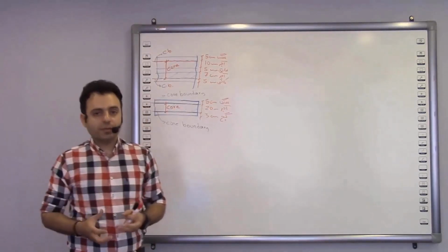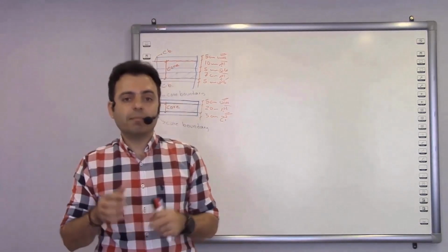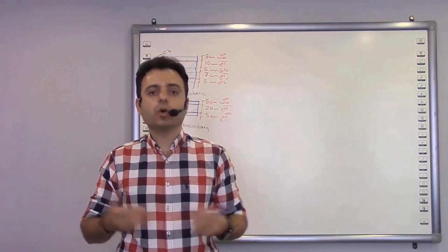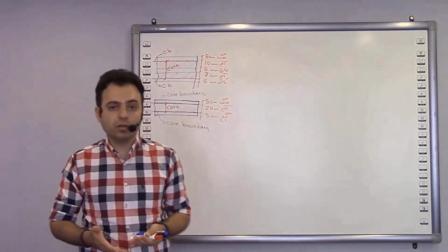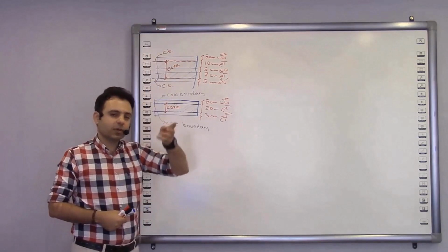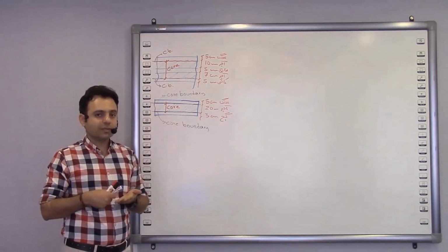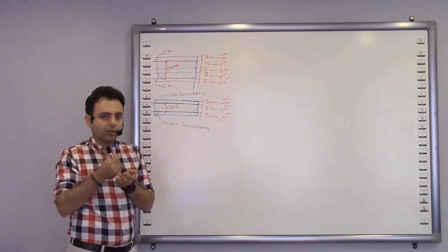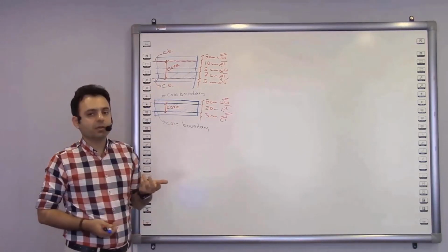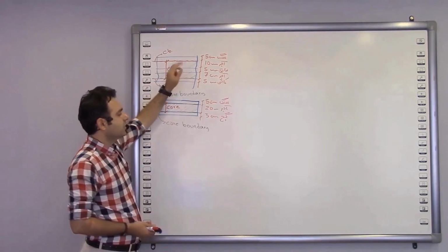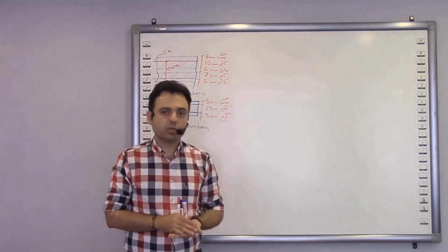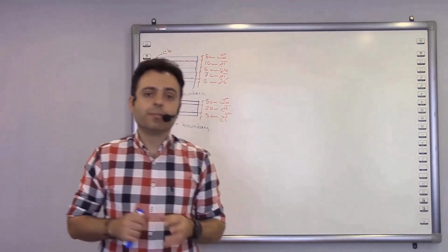Now let me tell you one more point and then we'll start drawing the walls. In the materials that are for finishing, do not use the cut pattern. Cut pattern must be actually inactivated. But why? Because the finishings are too thick, 2 centimeters, 3 centimeters, 5 centimeters. And if you draw patterns while printing, they will be black. Pattern, while thickness is little, will be definitely black. And I should also say that when your structure has patterns but no finishing, it's more clear. So we don't use patterns in the finishing materials.